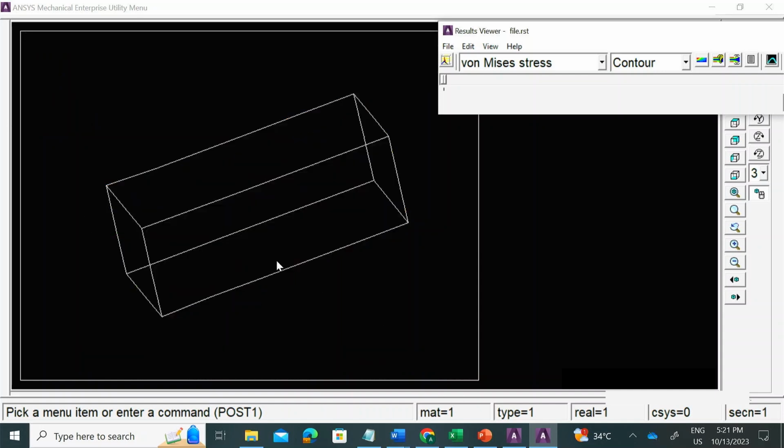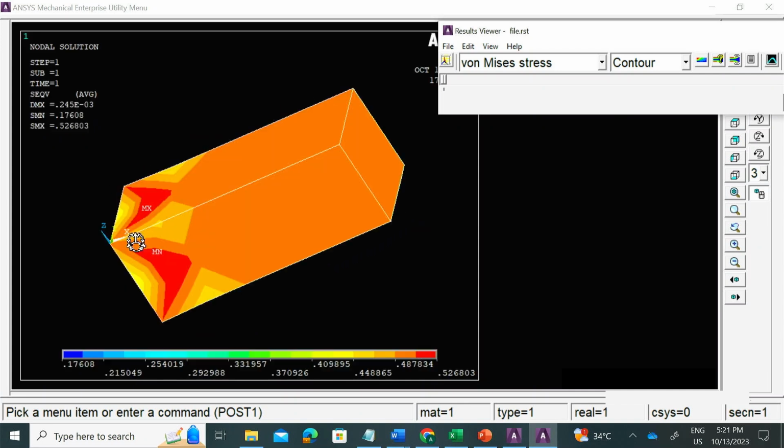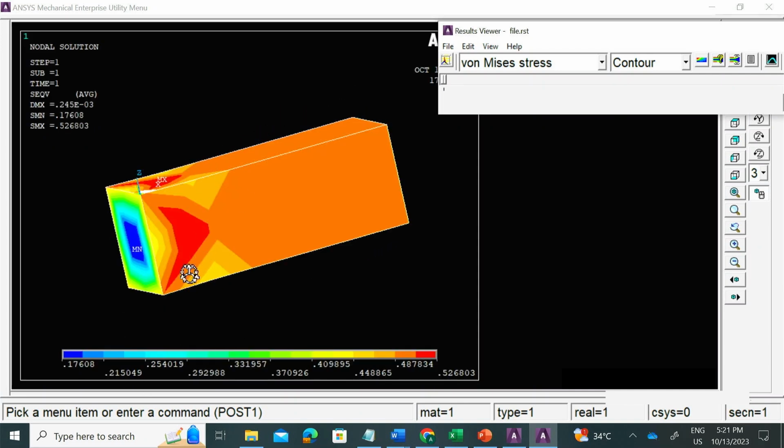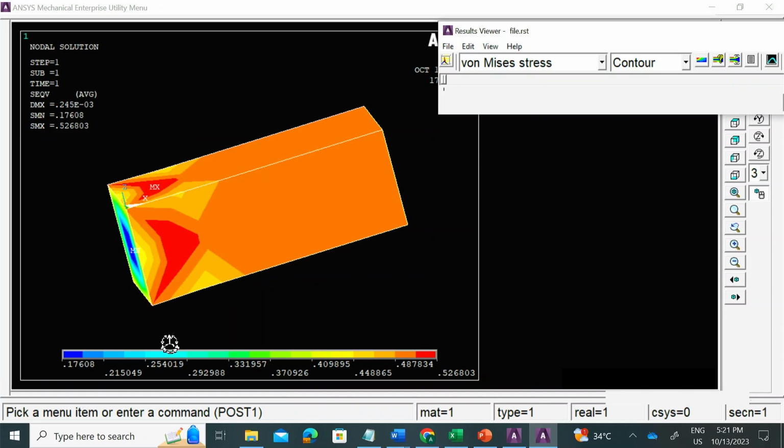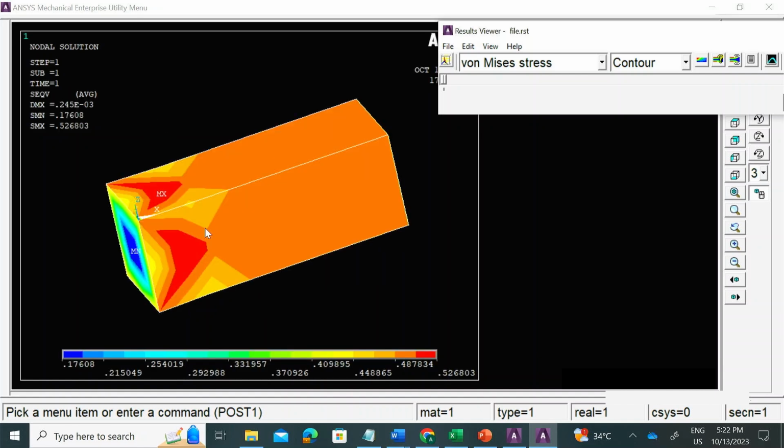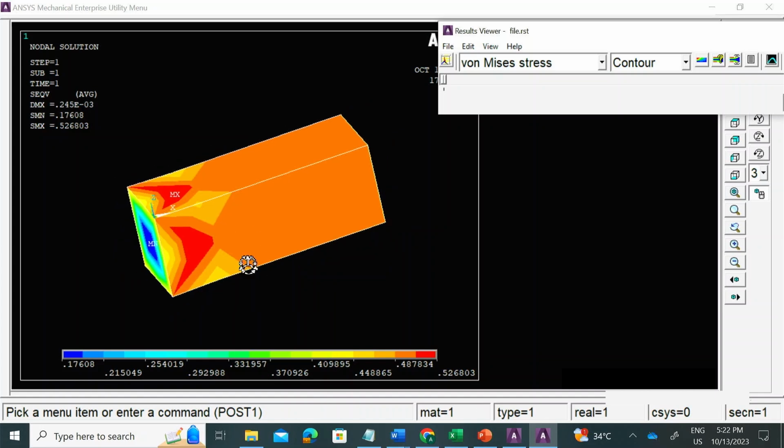And this is the distribution. This is of concern because whenever you have an area of very high stress with zones of very low stress around it, it can create fracture, but that is not the case here. You see a fairly uniform distribution. The red is transitioning into yellow and then to green and so forth, right? And also the values of stresses are super low. It's not going to create any damaging effect.